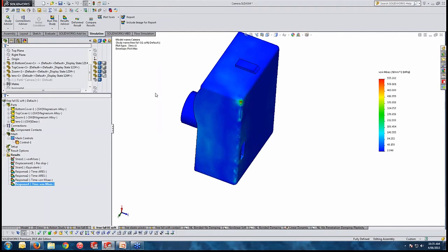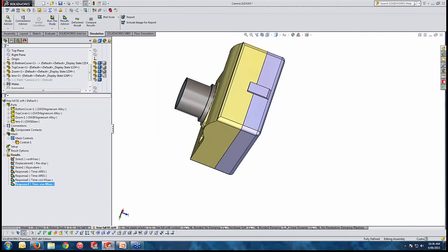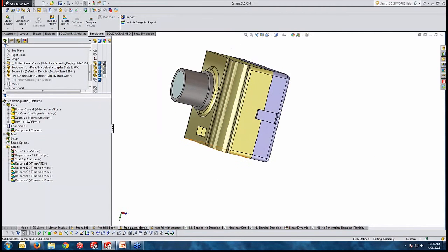Now we are trying to make the case as close to reality. That's why I'm going to have the third case study. Well, this time, as we know, when such an impact is happening, we have some permanent deformation, or let's say one of the materials is going to permanently fail and we have plastic deformation on it. Therefore, the material should be modified to capture the plastic deformation on the model.